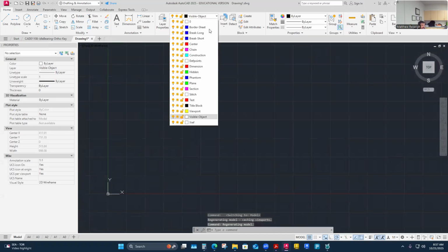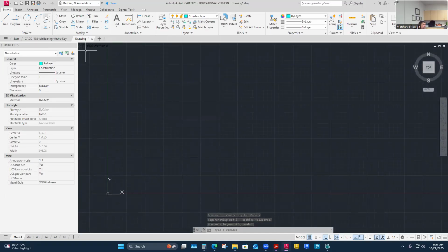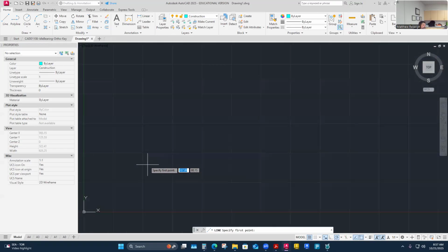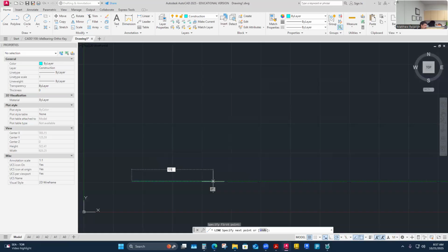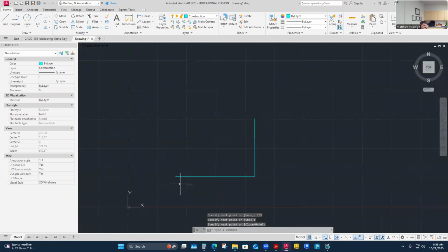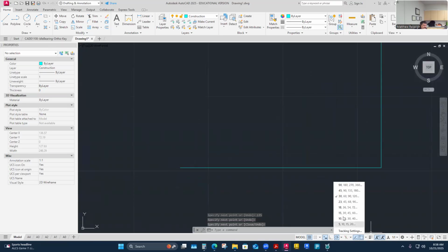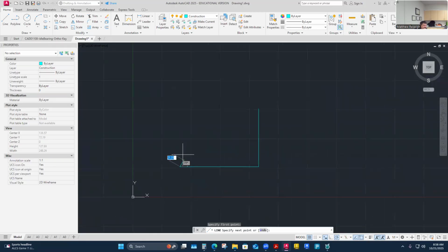Let's see. Do some construction work. I might piece this box together rather than draw a rectangle for myself, but you can draw this however you want. Because the one thing I do know is this dimension, 135, is at least how far it is. And the height, I don't know. It's going to go up some height here. So I think I'm going to come over here. I want to make sure that I'm able to draw at 30s and 60s or 120s because I have that angular measurement in my given information that it will be 120 degrees like this.